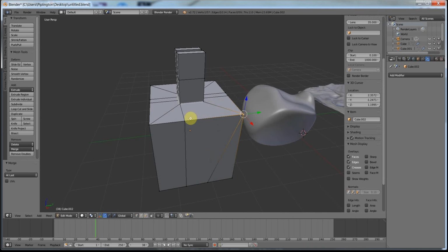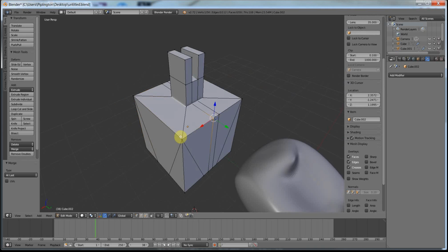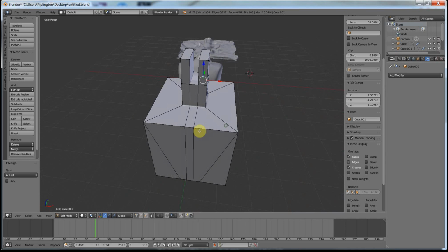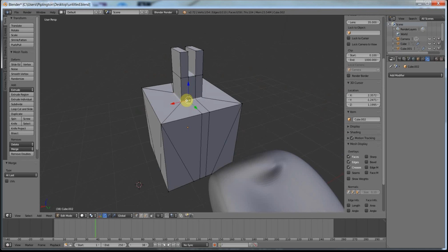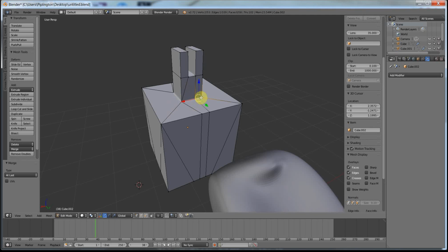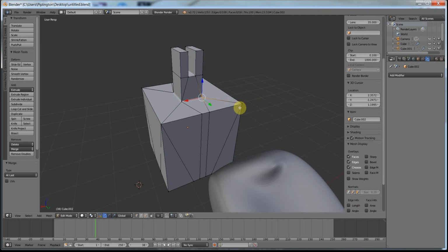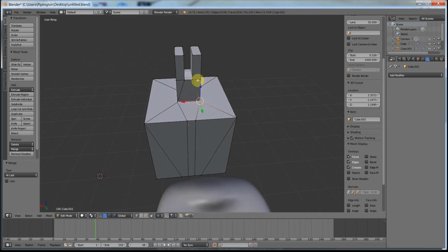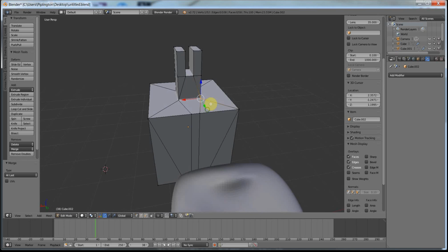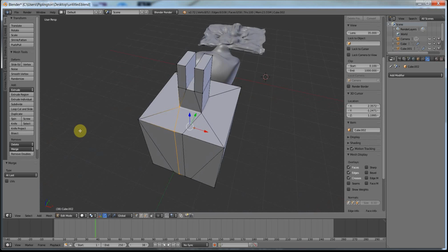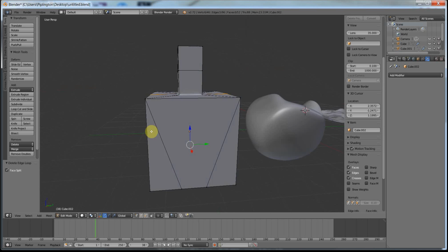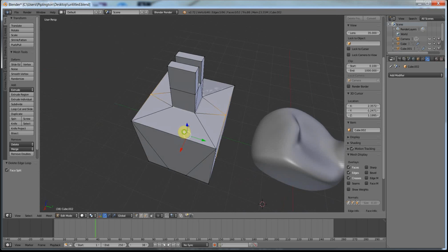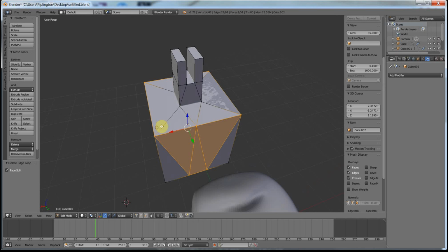So we're going to bring all these corner pieces towards a relevant edge, and then these middle ones again, well, we're going to do it here instead. Which is why I created this shape, because it's got this part in the middle and it's got edges that we can't just select and delete. But now I can select this entire edge loop and delete the edge loop, and it should work it out, but it's messed it up a little bit there. So I'm going to see what it does if I delete that again.